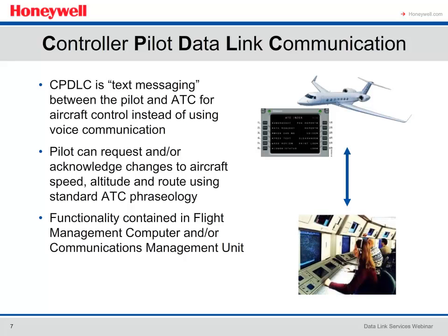The first service that we'll look at is a popular subject, which is Controller-Pilot Data Link Communication, or CPDLC, which allows for the exchange of text messages between aircraft and air traffic control instead of using voice. This can be especially helpful when operating in oceanic or remote areas and even in congested airspace. Pilots can request and/or acknowledge changes to aircraft speed, altitude, and route using standard ATC phraseology or standard text messages. This functionality is usually integrated into the FMS software or a communication management unit and may utilize SATCOM and/or VHF data radio.